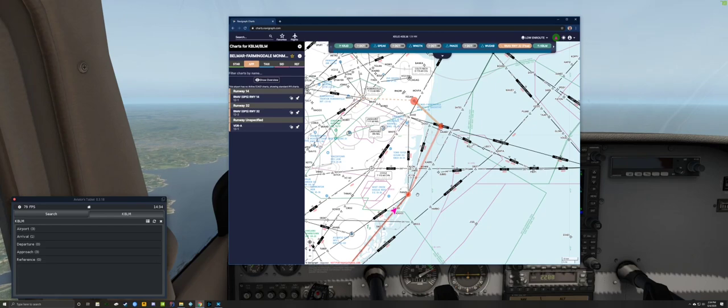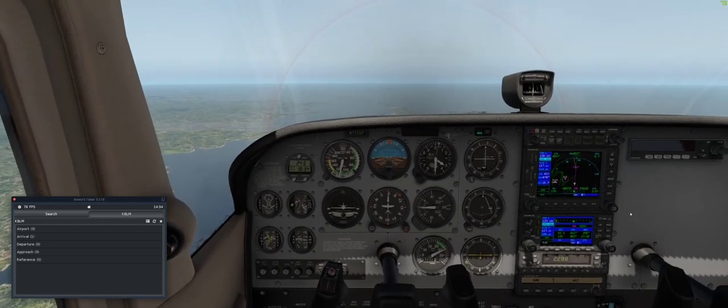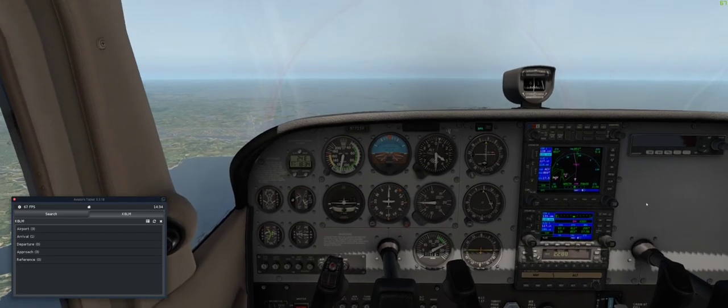And I said earlier, we'll take this chart away for now. I said earlier that the aircraft, this autopilot does not control your throttle. And it does not have a VNAV autopilot profile like the bigger aircraft, where you do your flight plan and you plot your course, LNAV, and your VNAV profile, and then the aircraft autopilot follows it.